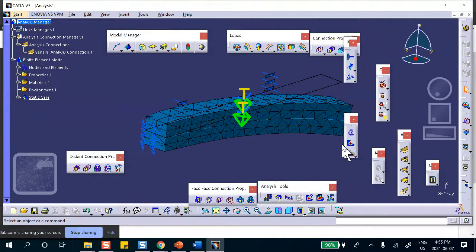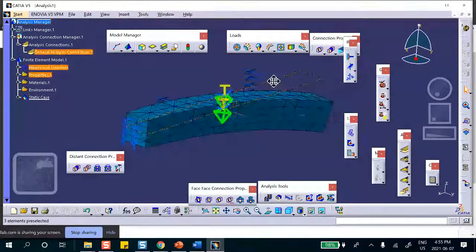And the reason is that the coefficient of thermal expansion of aluminum is bigger. It tries to grow more, and the steel says no.